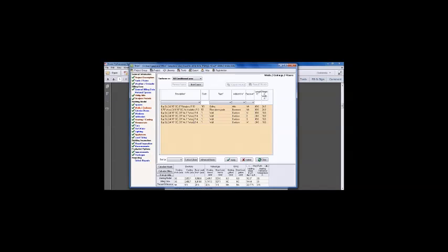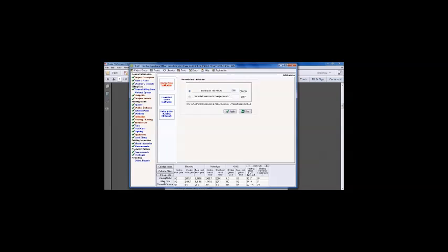Did you assume that the walls were uninsulated, but you never verified it by cutting a hole into the wall or something? You just did a quick IR scan and thought all walls are uninsulated. So it's the sleuthing process that really helps you double check: did I just make a bad assumption, or did I miss something completely? I had the square footage off accidentally. Or I put my blower door in as 2,200 when really it was actually 1,200. It was a simple input mistake as I keyed it into the computer.